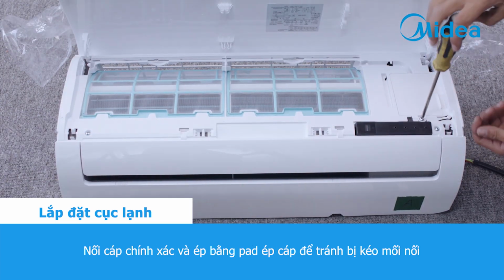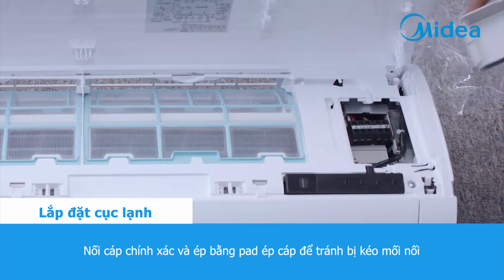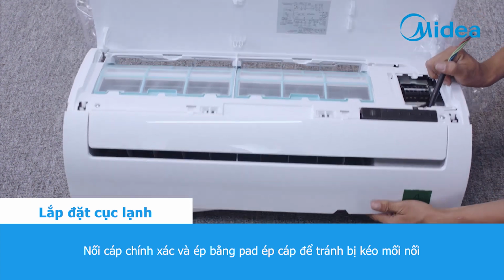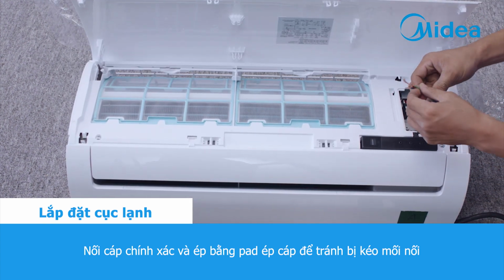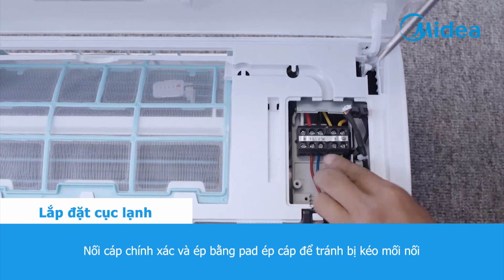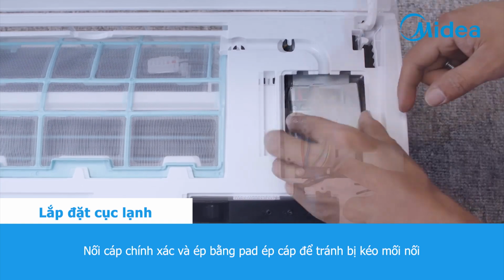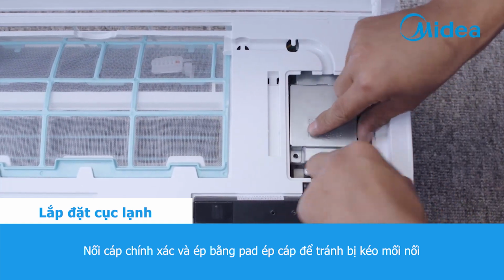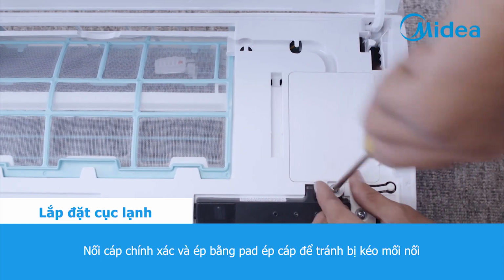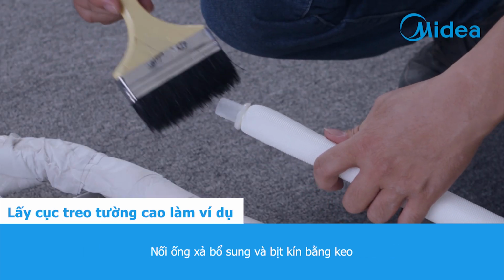Make correct connection of cable and press it with pressing pad to avoid the connections being pulled. Connect the extra drain pipe and seal it with some glue.